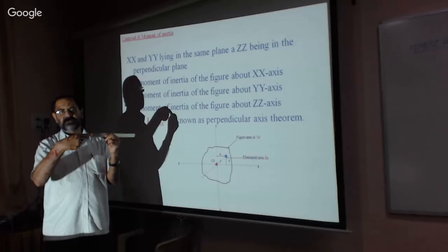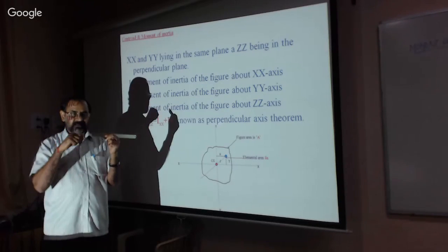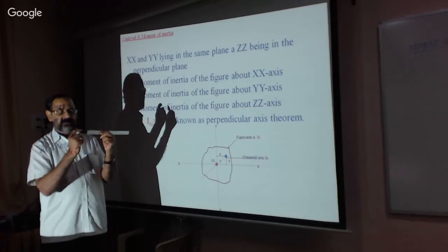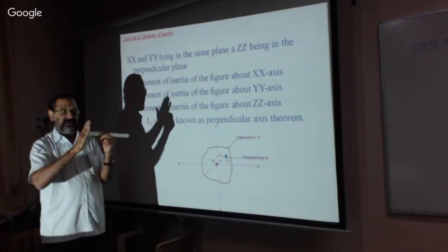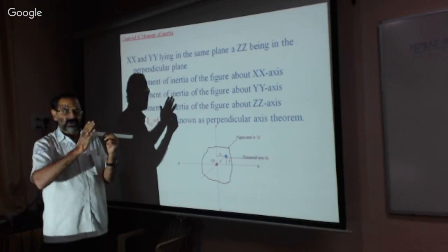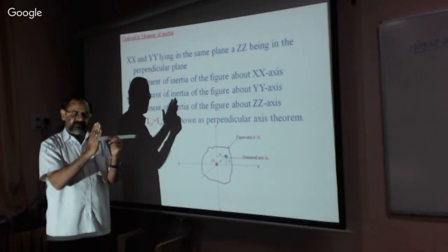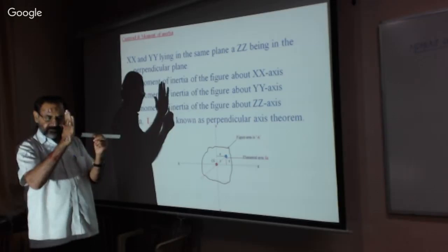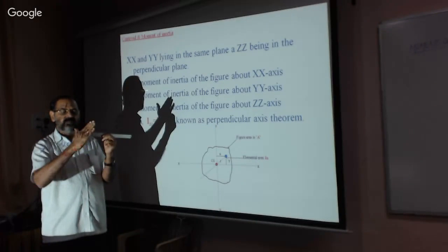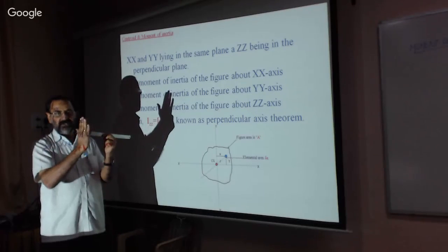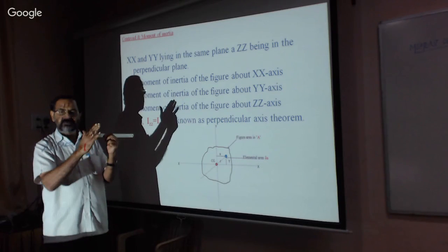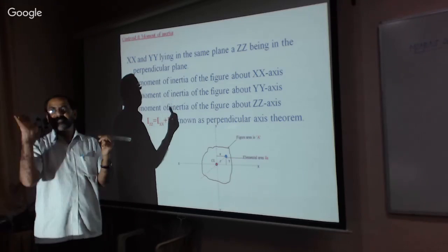Now let us understand clearly how the section behaves about the x-axis. Because there are a number of sections placed, and the depth is more, this is more rigid in this direction. Therefore, along the x-axis, the resistance of this beam is more.